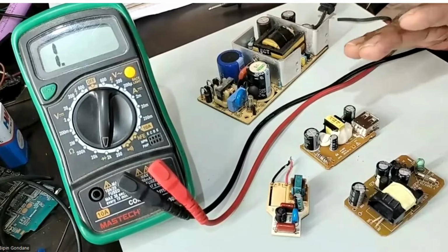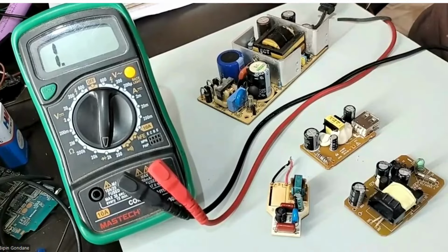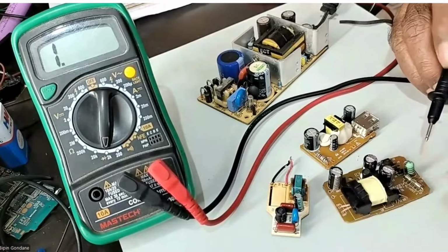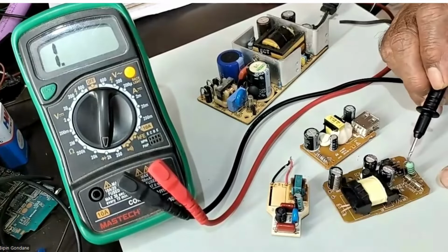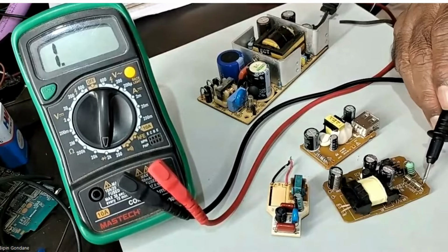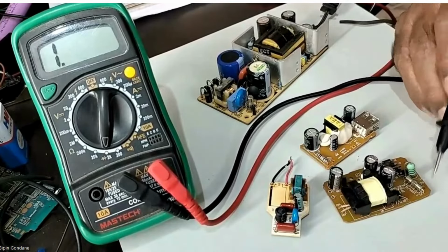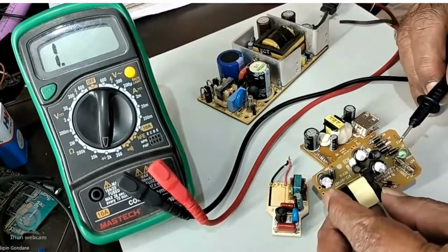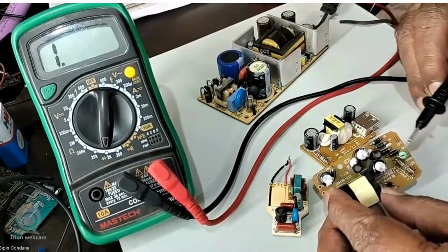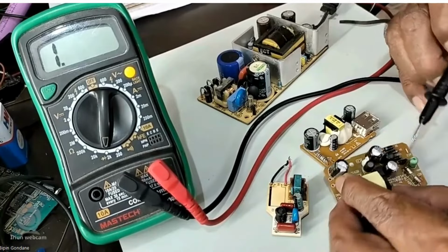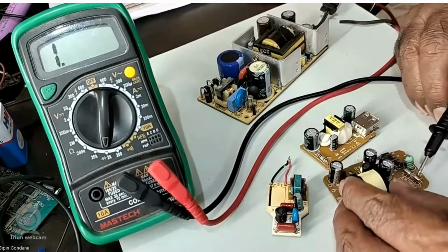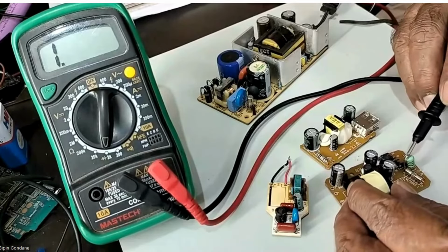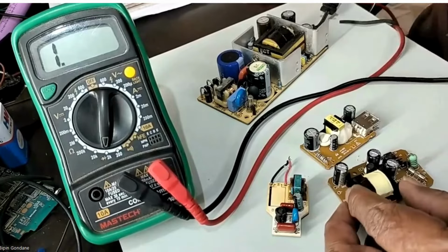I will tell you what the important parts are that you have to understand first. How will you identify where to start if some board comes for repair? First of all, you have to identify where the AC comes in. Suppose these are the AC terminals, written AC1 and AC2. You identify these two terminals and follow what is connected to them. That is a fuse and some inductor coil. So you have to check the fuse.